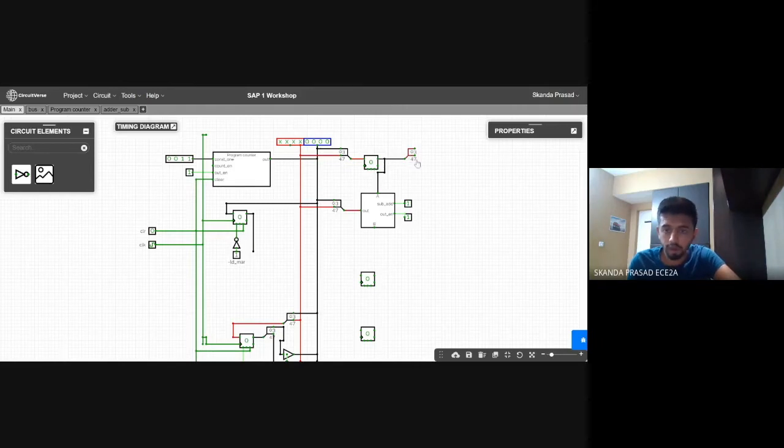Before I split it, I just need to do one more thing. That is a tri-state buffer, because anything that goes onto the bus has to be given through the tri-state, right? We have discussed that before because we don't need contention. I've already told this numerous times, and so have my teammates, but I had forgotten that. So search for tri-state, connect to the tri-state, and then take its output. Give an enable. We'll name it in a second.